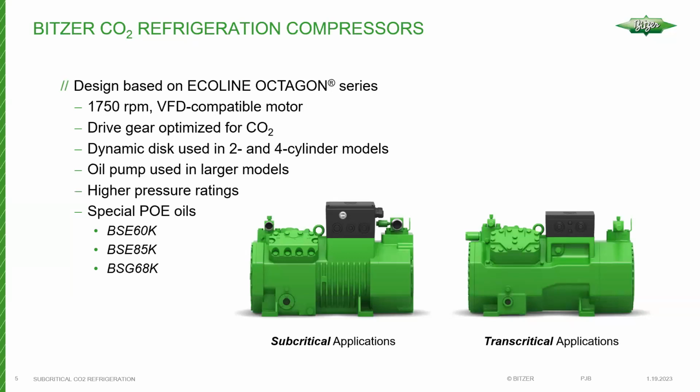CO2 applications involving Bitzer compressors also require special oils. As I said before, POE oil and CO2 have a very high miscibility. So one of the ways in which to mitigate this is to start out with a higher base viscosity, because we know there's going to be more CO2 in that oil at any given point in time.